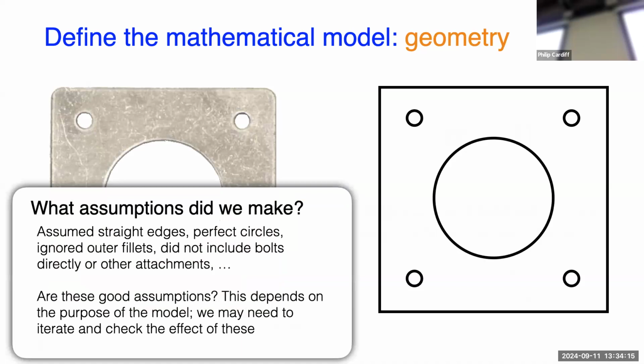The key thing here is I'm just trying to say that you can always keep including more complexity, but that's not the goal here. The goal is to make a model that's useful. And then if it's not useful when you create a simple model, then you go back and add more complexity. The wrong thing that people do, and many of you will do in simulation parts of your thesis project, is you might try to make a crazy complicated model, and then it doesn't work. Someone comes to me and says, your model didn't work. I'm like, okay, show me what we're doing. And then it's this crazy 3D model with millions of cells where I don't know what's going on. Get a simple thing working. You can always add to a simple thing that works rather than start with a big complicated model that doesn't work, because that's just useless.